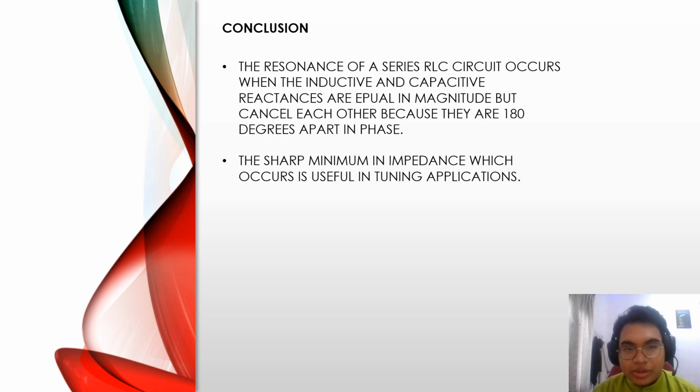For conclusion, the resonance of the series RLC circuit occurs when the inductive and capacitive reactance are equal in magnitude but cancel each other because they are 180 degrees apart in phase. The sharp minimum in impedance, which occurs, is useful in tuning applications.